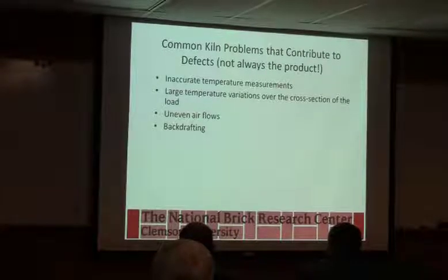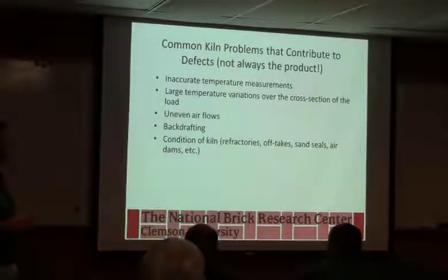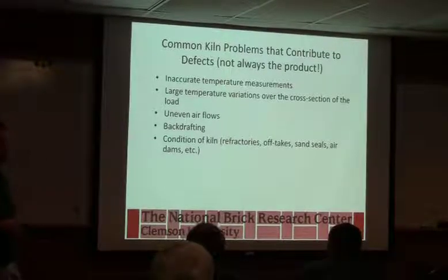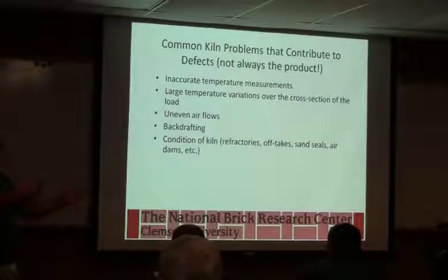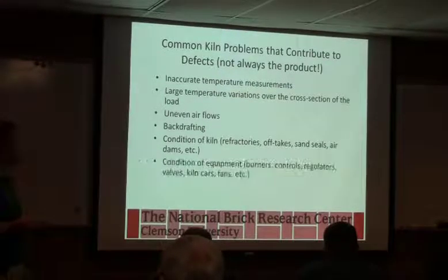Backdrafting can also lead to issues if it's not done correctly. Condition of kiln, the refractories, the offtakes, the seals, the dams, if you have air leaks, those can all affect the profile of not just the overall car, but individual areas of the car, which will give you a lot of variation in the cars.